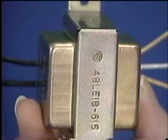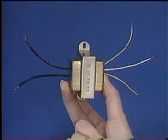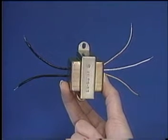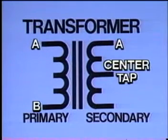Another component that can be tested for continuity is the transformer. Notice that this transformer has 2 wires on the left and 3 wires on the right. The schematic for this transformer shows that the wires on the left create one continuous path between points A and B called the primary winding. The 3 wires on the right also create one continuous path between point A, the center tap, and point B. This path is called the secondary winding.